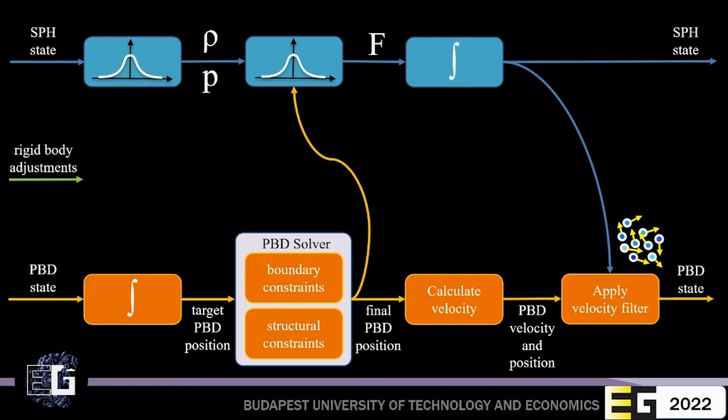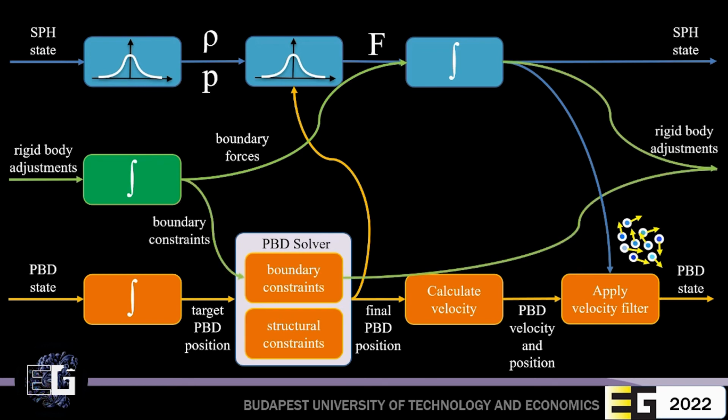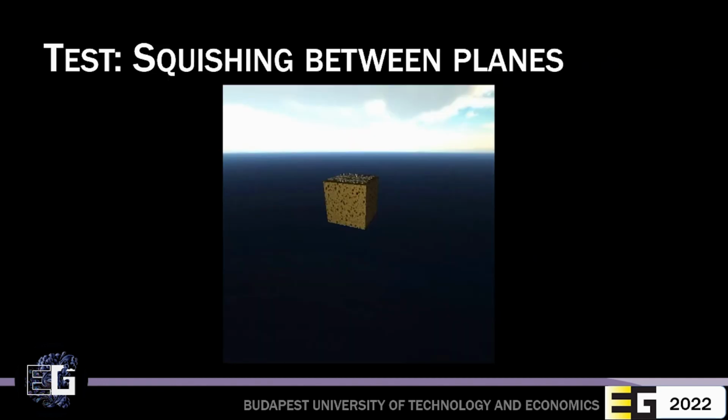Rigid bodies on fluid effects are formulated as repelling forces. Rigid bodies on sponge effects are contact constraints. Both sponge and fluid on rigid bodies are resolved using PBD, adjusting rigid body pose to match constraints against fluid particles and solid nodes. Here, the invisible planes move with constant velocity and are not pushed back by the fluid or the sponge. Also, after the invisible planes effect is turned off, the sponge recovers its original shape.